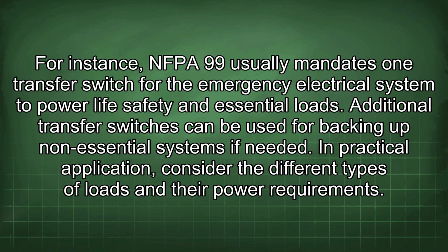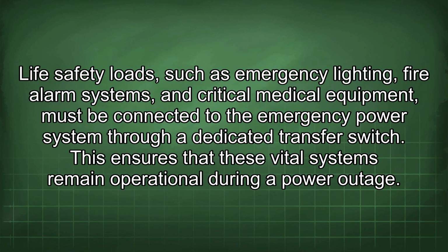In practical application, consider the different types of loads and their power requirements. Life safety loads, such as emergency lighting, fire alarm systems, and critical medical equipment, must be connected to the emergency power system through a dedicated transfer switch. This ensures that these vital systems remain operational during a power outage.